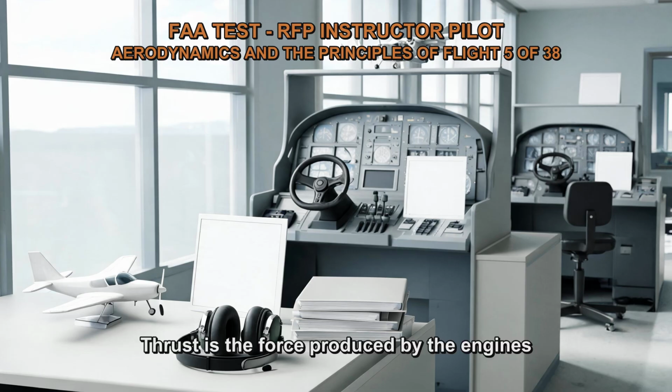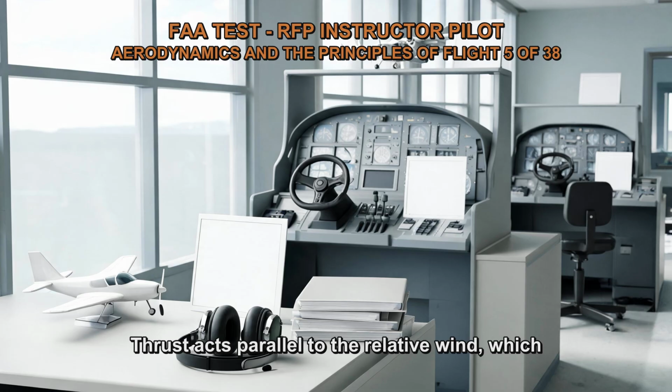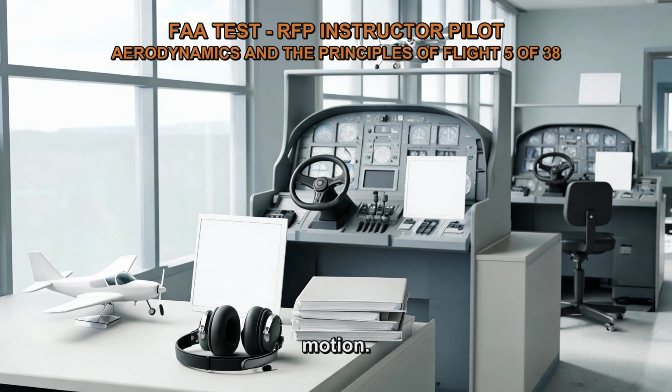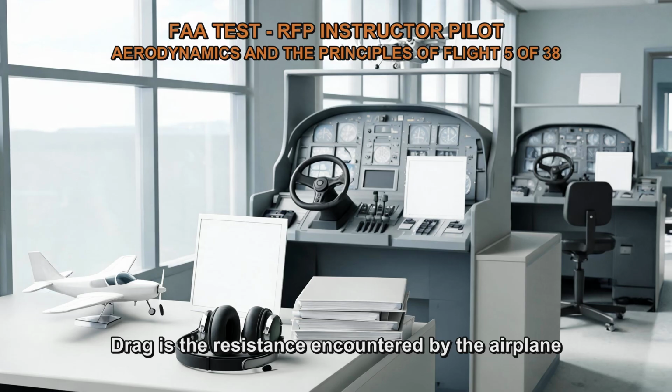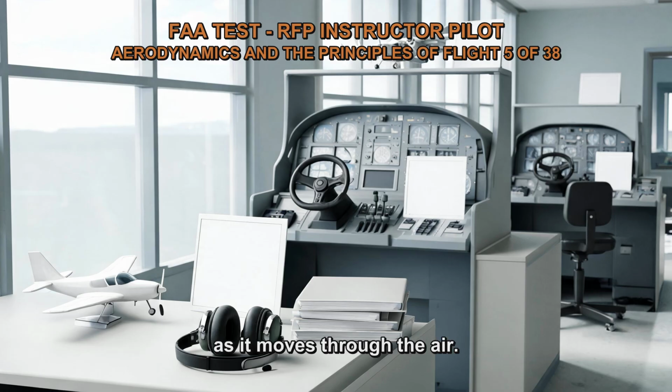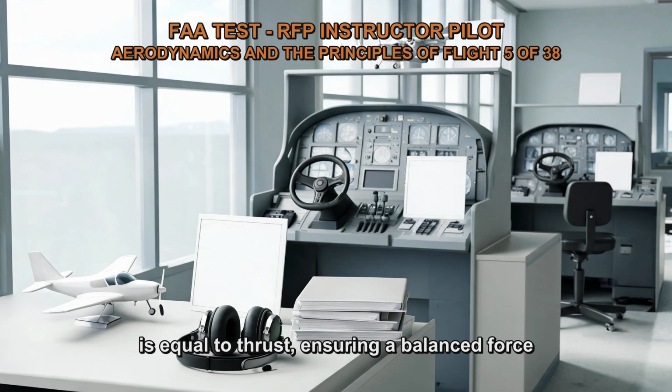Thrust is the force produced by the engines of the airplane, propelling it forward. Thrust acts parallel to the relative wind, which is the airflow created by the airplane's forward motion. In order for the airplane to maintain a constant airspeed, thrust must be equal to drag. Drag is the resistance encountered by the airplane as it moves through the air. It acts opposite to the direction of motion and is caused by various factors such as air resistance, skin friction, and induced drag. In straight and level flight at a constant airspeed, drag is equal to thrust, ensuring a balanced force situation.